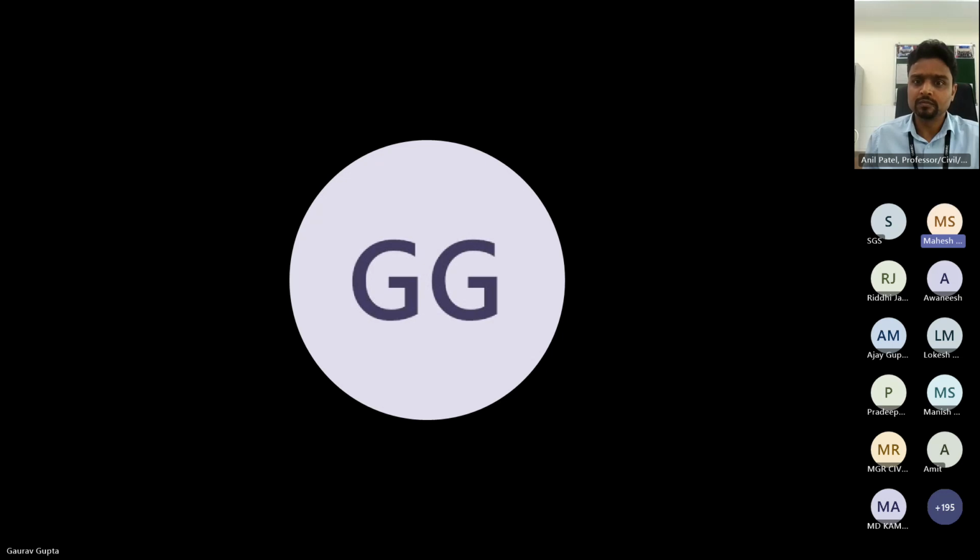Actually, for the couplers, we have no option for staggering because it is a junction of D wall and slab, right? So where we have a choice, we should have staggered. But where we have no choice, because the D wall is done first, then the slab, we have to keep all the couplers on the same level, same line. Normally we should provide 10-20% extra if possible, to save some extra margin. But we don't have a choice.